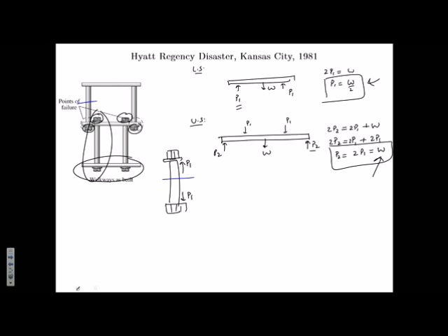Right? Now, there are certain areas where you cannot have a very large factor of safety despite human beings being involved. Can you think of any scenario like that? Aircraft. Weight is at a premium. Jet fuel is expensive. So the aircraft companies are trying to reduce the weight as much as they can. That's why you have to pay for that extra bag when you travel these days, right? So that's why they're trying to design the material, using composites, changing the geometry, doing topology optimization to make the structure as lightweight as possible without sacrificing strength. Right? But based on what we have done, this is something that we could analyze and see where the problem would be.